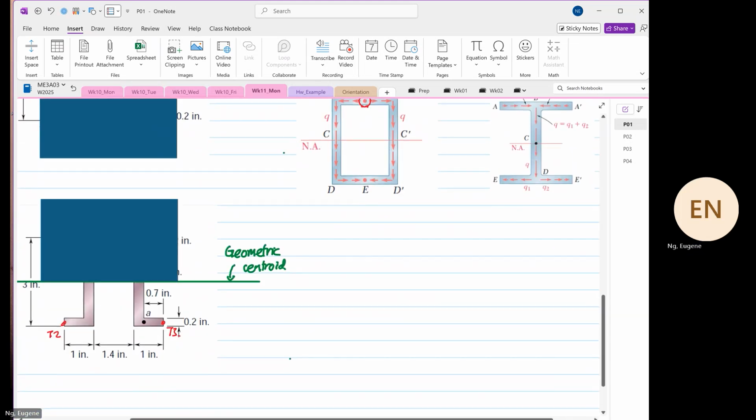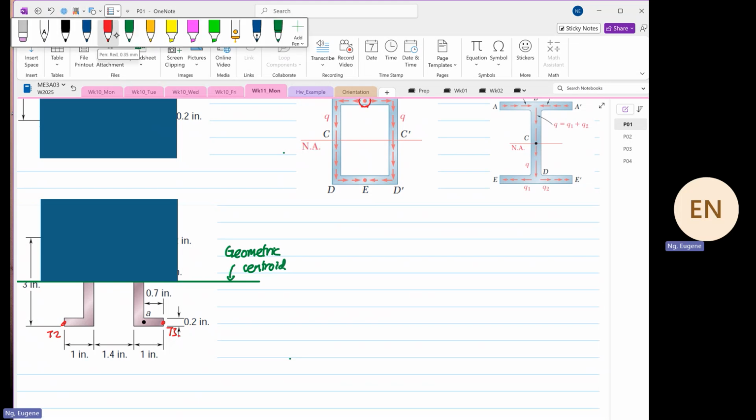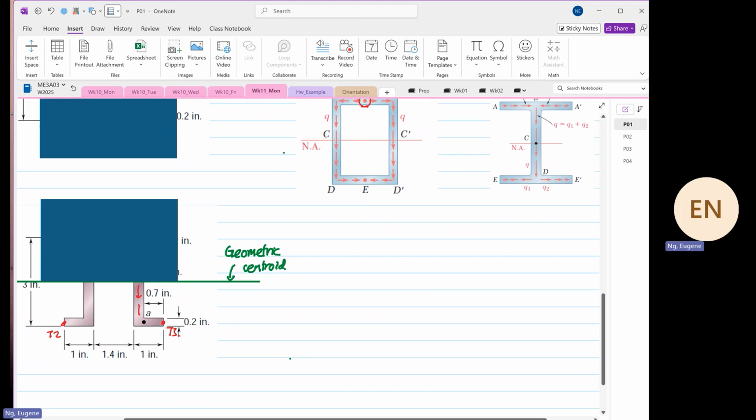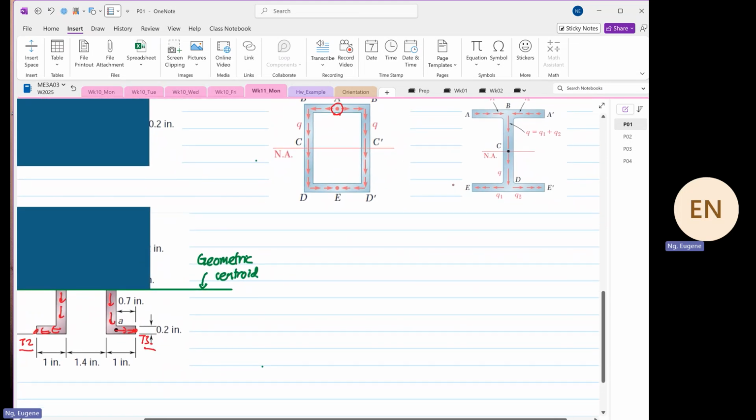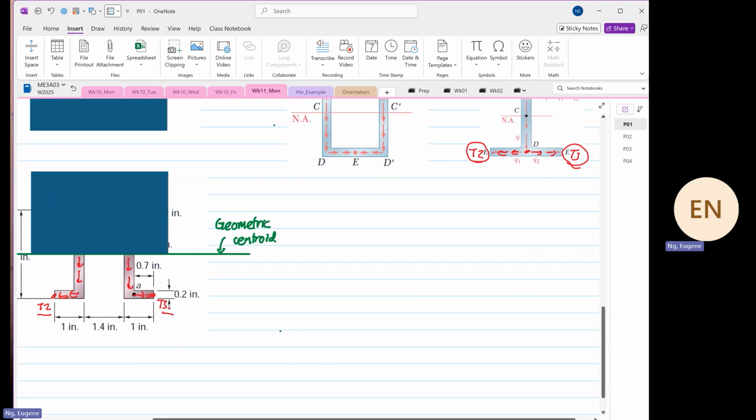Okay. And now if we were to sketch the bottom part of our analysis, we know that the shear flow will go this way, and we know that the shear flow will go this way. So we have two terminals down here. And if you look at the white flange, you have two separate terminals down here also, where you have the split. Yes or no? More important, we finish off with two different what? Terminals.